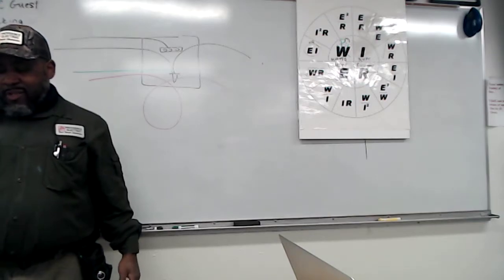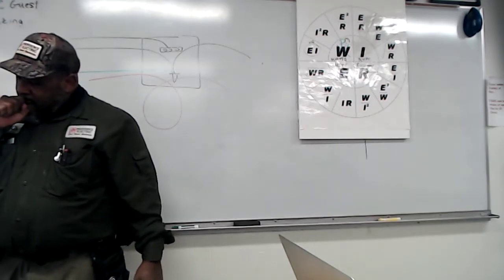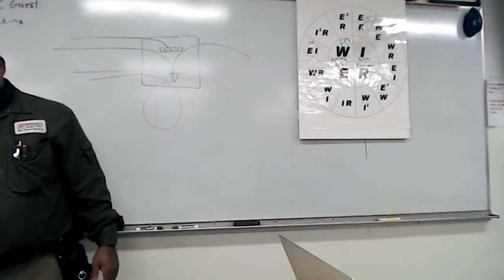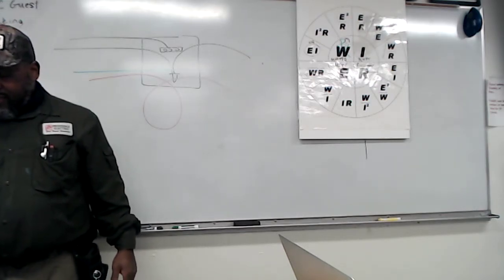Number 3, rule number 3. I don't know why I got 4, but anyway. Where one or more luminaire studs or hickeys are present in a single box, it gets one allowance. It gets a single allowance.